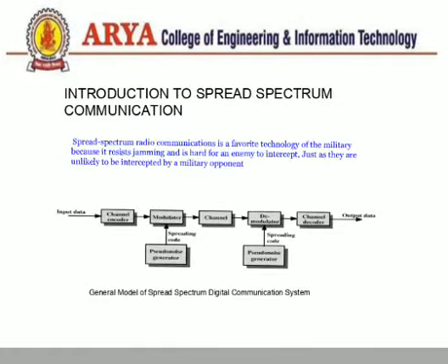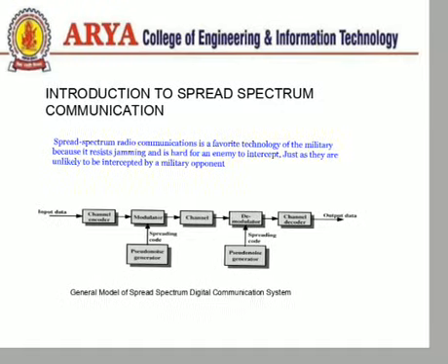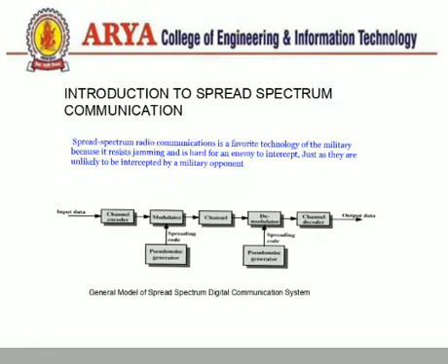First, introduction to spread spectrum modulation. Spread spectrum technology was initially developed for military and intelligence communications to overcome the two shortcomings of interception and jamming. The basic idea was to expand each user signal to occupy a much broader spectrum than necessary. An important aspect of spread spectrum modulation is that it can provide protection against externally generated interfering signals with finite power. Spread spectrum techniques involve spreading the signal bandwidth B over the complete available bandwidth B total.